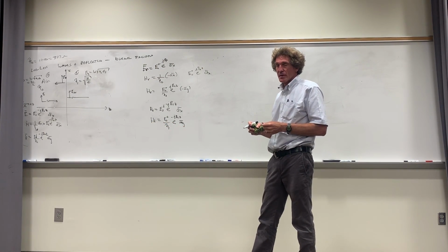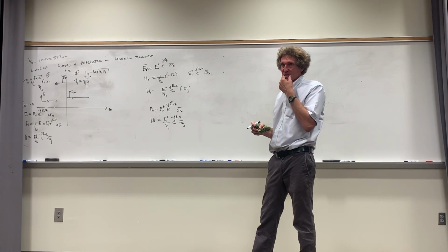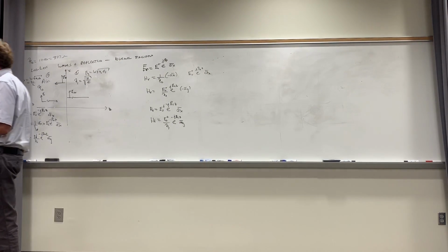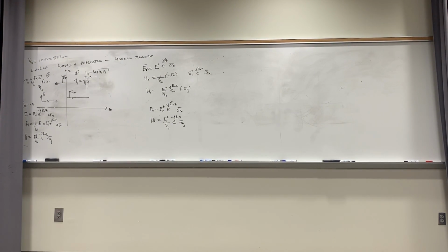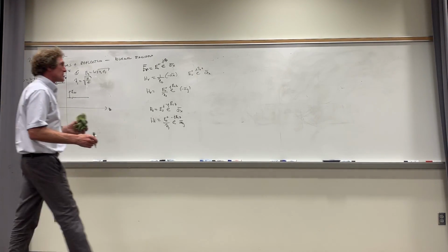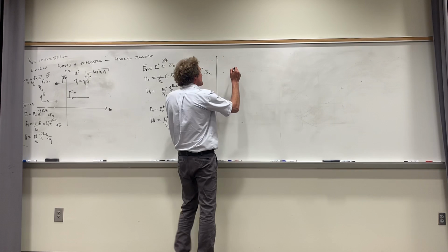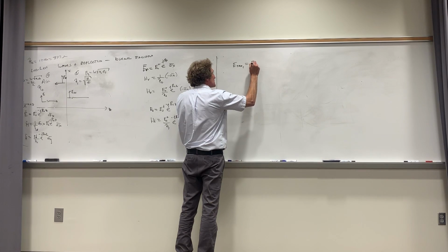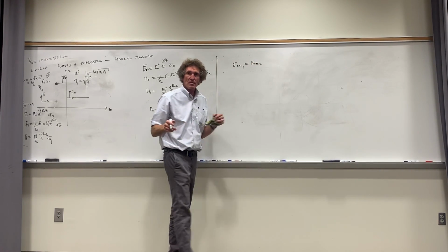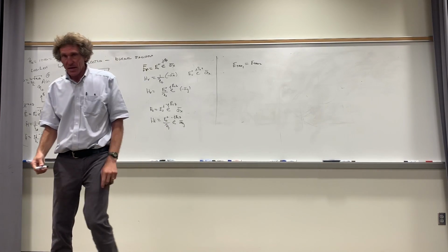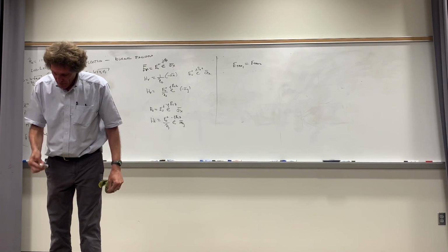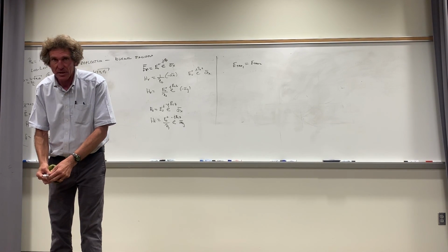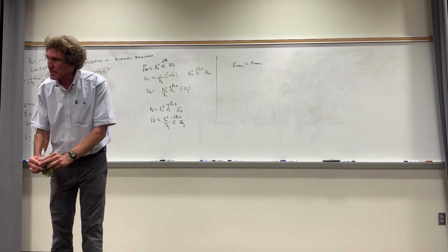Are you with me? Now here's where it becomes important you see this. The way we figure out what we call the reflection coefficient or transmission coefficient is we equate the values of the electric field at the boundary. You've heard this in EMAG 1. Do you remember E tan 1? The tangent field in region 1 was equal to the tangent field in region 2. Do y'all remember that? Now what is tangent? Well, if I'm talking tangent to this floor, it would be something in the plane of the floor. Like if an electric field had this orientation, anywhere in the horizontal direction, it would be tangent. Normal would be perpendicular, this way.